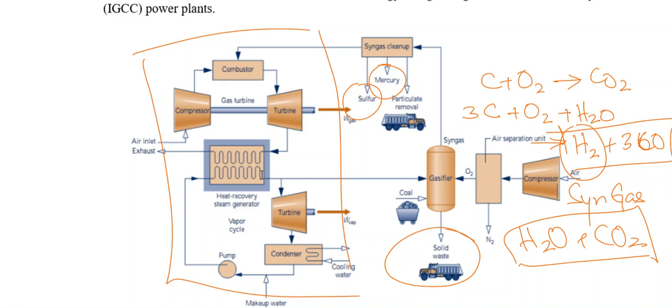As said earlier, the coal would not be reacting completely but partially with the oxygen. So there should be an environment in the gasifier which will provide energy to react the carbon with oxygen, not completely, but to produce carbon monoxide and H2. So this type of chamber is called a gasifier. For the gasifier, we are supplying only oxygen, and that is oxygen from the air.